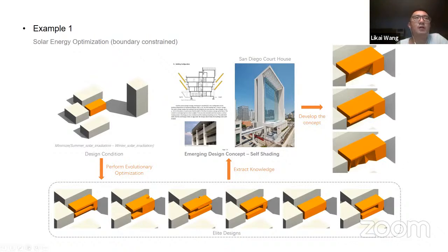When we run the optimization here, there is also a context. The urban context has a high-rise building in the southeast corner and three middle-rise buildings in the west and the north. Then I ran the optimization and got the result from the SSIEA. I used 6 subpopulations, so I can get 6 design solutions in the optimization result. And we can find that all of these solutions share a feature: they have something like self-shading in the west part of the southwest surface of the building.